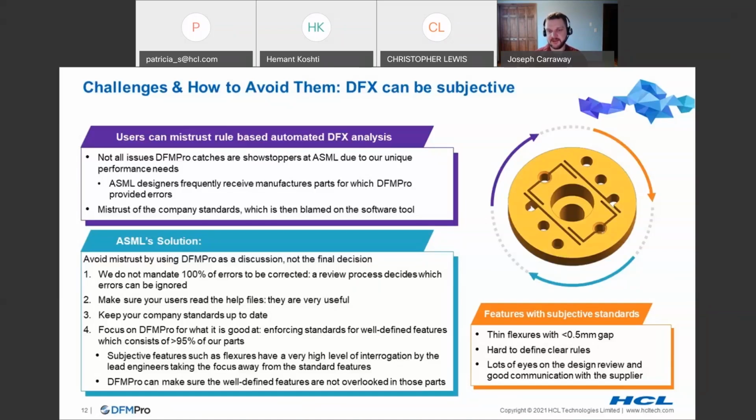And you could tell that by reading, hey, this is an 850 millimeter depth of cut, where the designer thought it was a 40. The software was actually assuming that you were machining the part from the opposite side of what the designer thought. And this is because there was an overhang in the part. They spent a couple days looking at this error, and then I told them, read the message, and they finally understood.